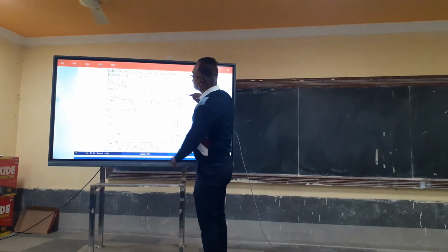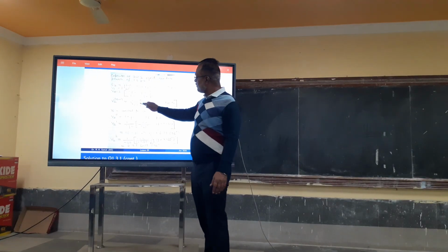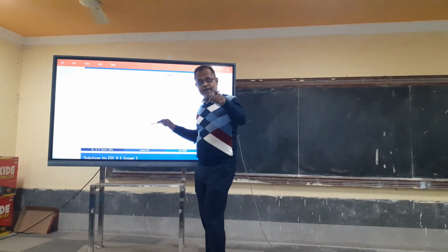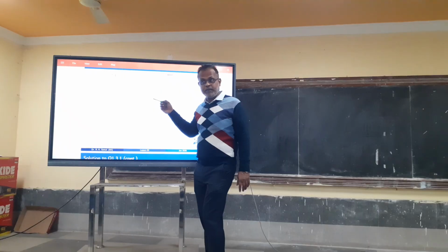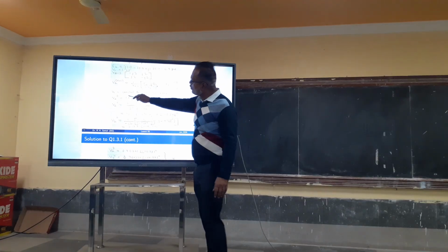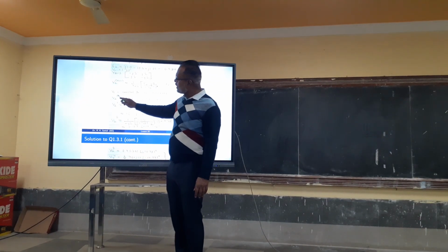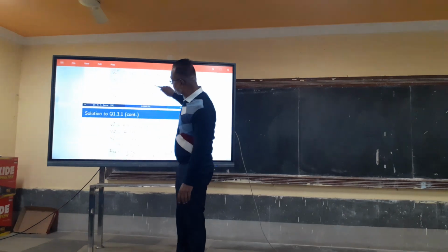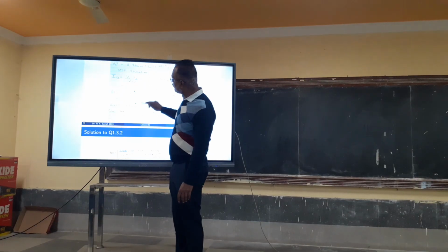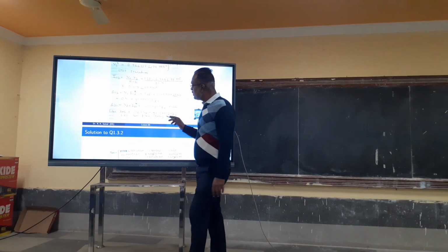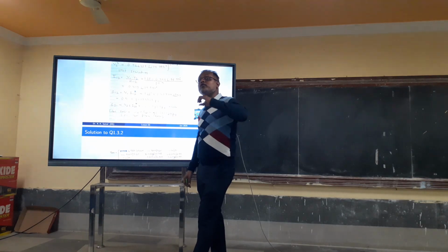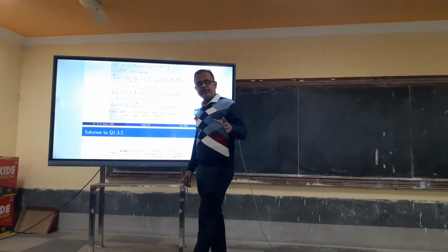See, in the first case, we are using the same formula and we are iterating. This is implemented in one of the codes in your lab. It's a very small code. If you do it manually, you have to use the voltage at the zeroth iteration, first iteration, second iteration, and so on. Then you compute current. Then you compute the power flow. Now you sum S12 plus S21, which is only reactive power loss in this particular case. There is no real power loss because we have not taken the resistance of the line.